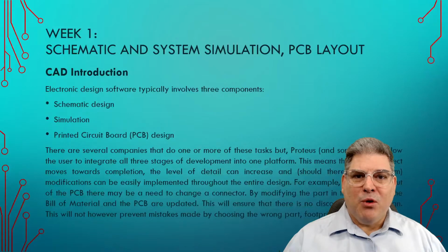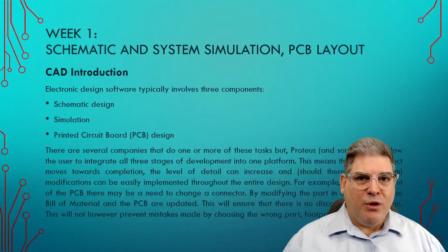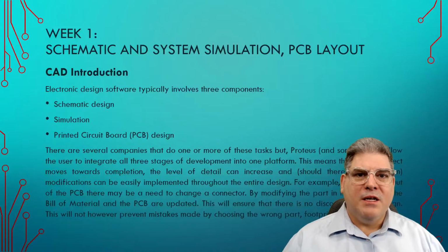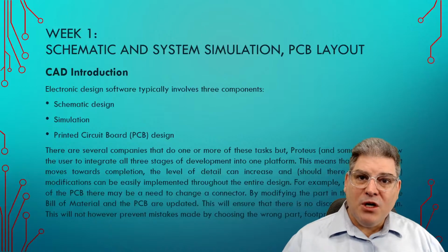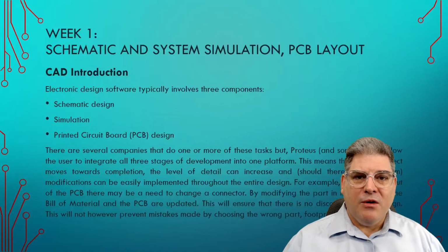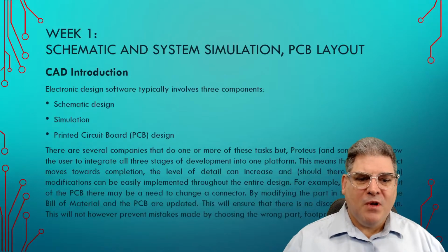Another thing that Proteus will not catch is if you actually put in the wrong footprint, it doesn't help you. So be very aware of garbage in, garbage out. Okay, Proteus is a great piece of software. I use it on a daily basis on my day job, as well as teaching it here at the college, but it does have its limitations as well. All right.